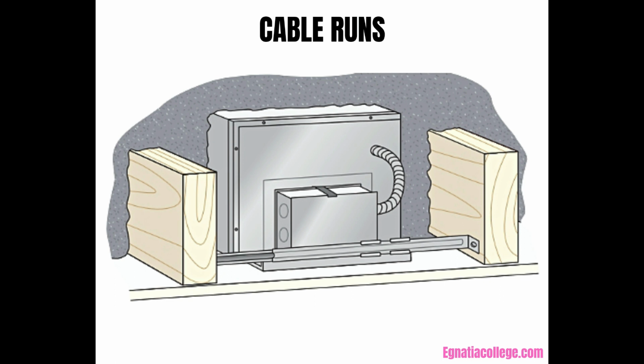When a circuit is run through a recessed fixture like the type shown in this figure in Unit 10, that recessed fixture must be approved for through wiring, a subject discussed in Unit 10. When you are unsure whether a fixture can accommodate the extra wiring for a run to another fixture or some other part of the circuit, it is best to design the circuit so that the wiring ends at the recessed fixture with just the conductors needed to connect it.